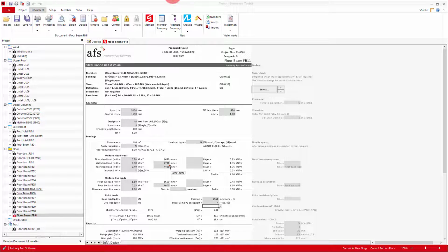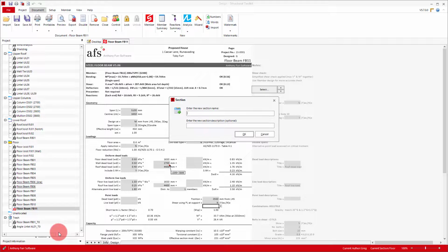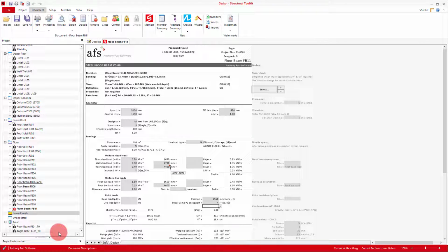We'll want to avoid 10mm thick members so that the builders can still feel some grout in between the bricks and the lintel. The easiest way to go about this is to work out the maximum span a 90 by 6 equal angle can go with our standard heights of bricks above our windows and openings. Looking at our elevations, we can see most windows have 900mm of brickwork above them, so we'll start with that. To begin with, we'll create another section to the left and open up an angle lintel document.